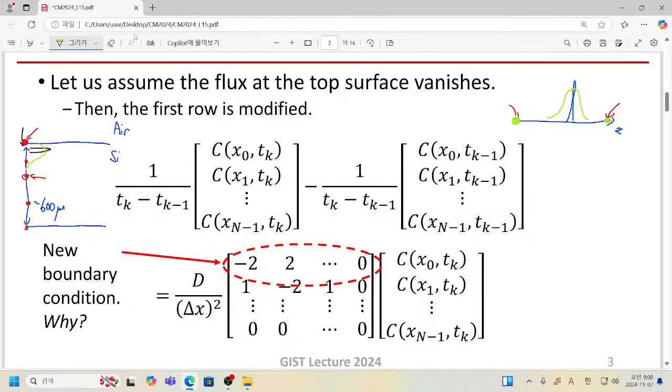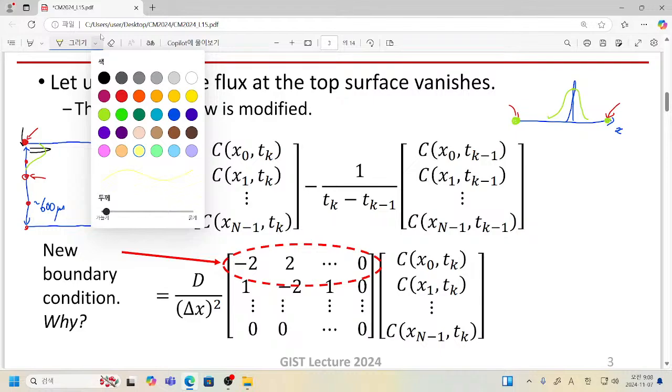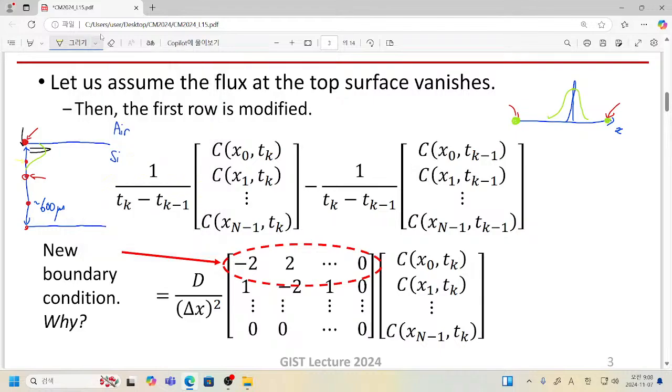If our final distribution looks like this, then a problem occurs when we select the boundary in this way. If we have this boundary point, that will certainly introduce distortion of our solution, so it is not desirable. However, if we select this way or that way, that doesn't make any difference in our numerical solution. So this boundary point can be well established and it's okay.